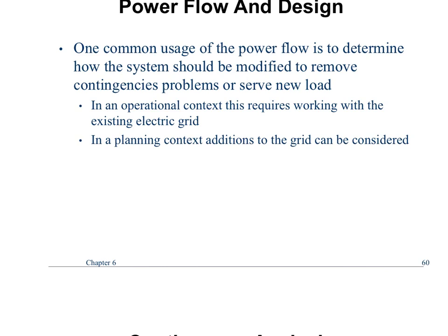Do I need to add another line? Do I need to add another breaker position? Do I need to increase or decrease the impedance here? And so if you go into ISO New England's website, there's something called a queue, where you basically say, I want to build a power plant at location XYZ. You fill out an application, you pay some money, and then you get a number. You're in the queue. And all the projects in the queue in front of you get analyzed first, and then yours gets tacked on after that.